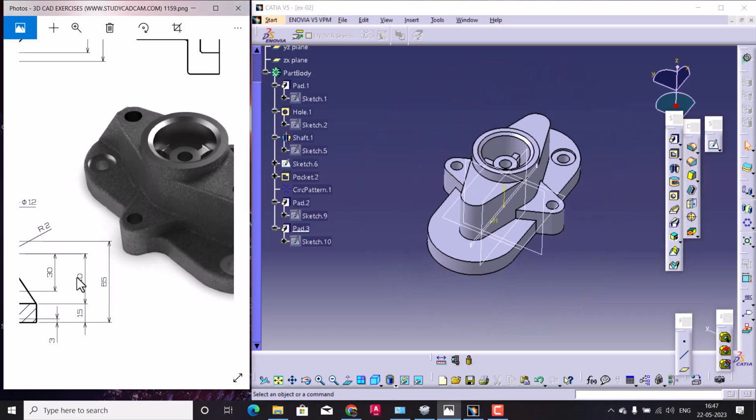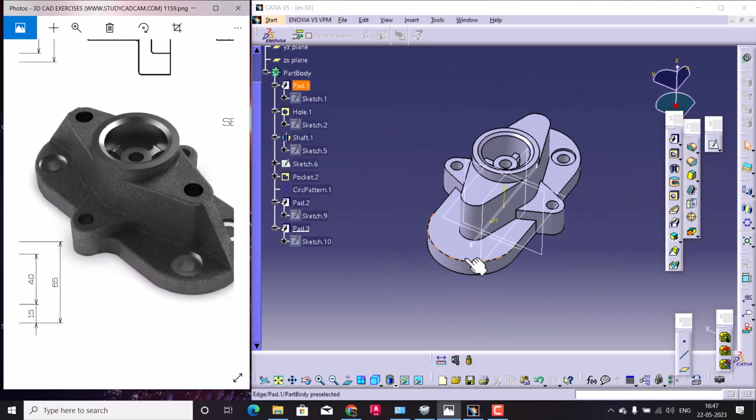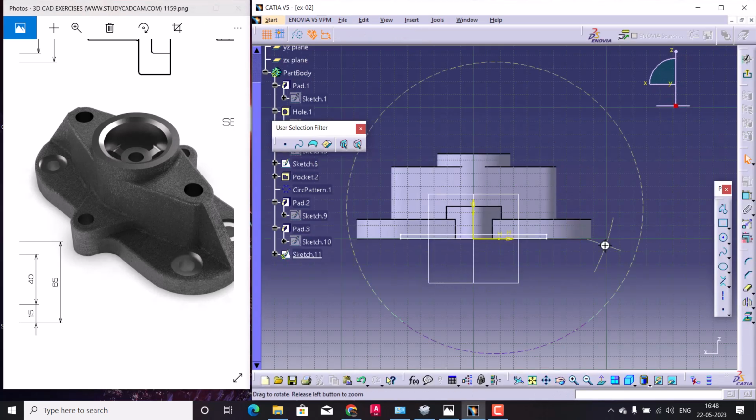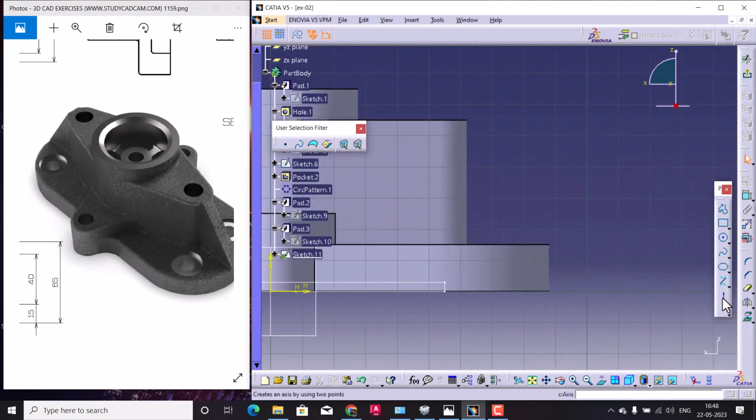So next is, I guess, the rib-like structure. So let us go on the same side plane. Then let us create a line. It has to touch this end and it has to touch that end. So let us start creating it, but before that we need this one. So project that, then project this also, then convert into standard element.